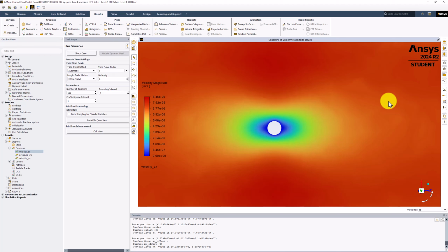This is characteristic of low Reynolds number flow, in which viscous forces dominate and the boundary layers stay attached. This means that the flow does not separate and recirculate behind the cylinder. As the velocity increases, we would expect this rear low velocity region to grow as the flow separates.